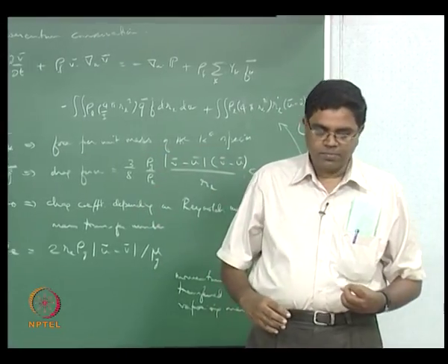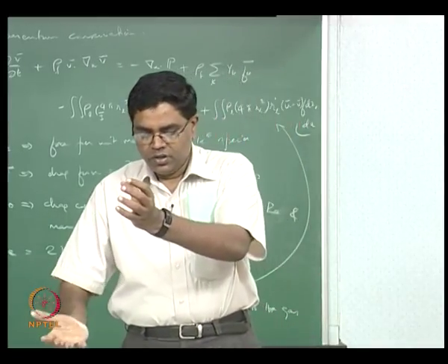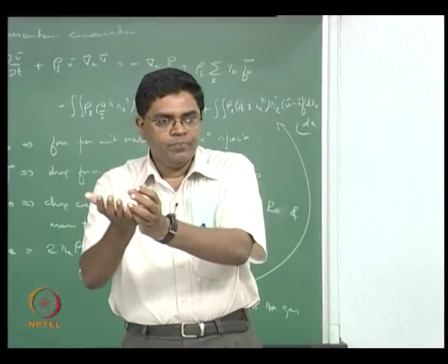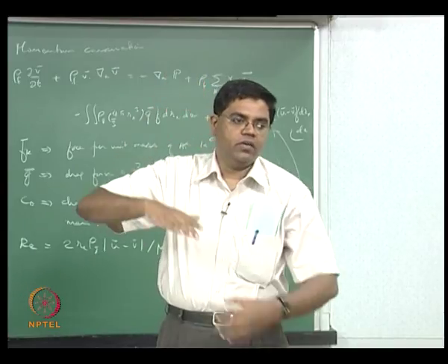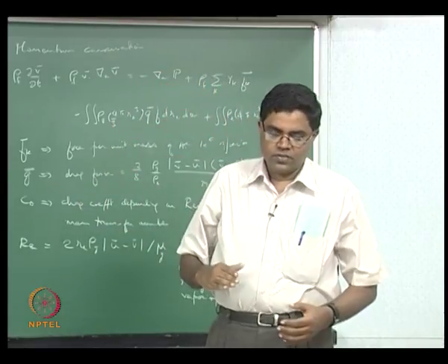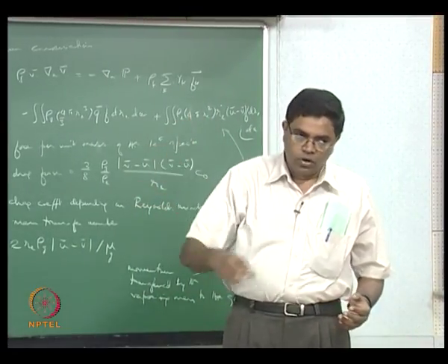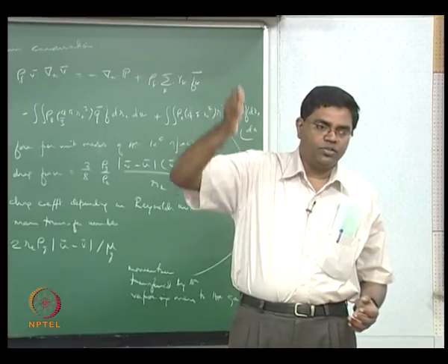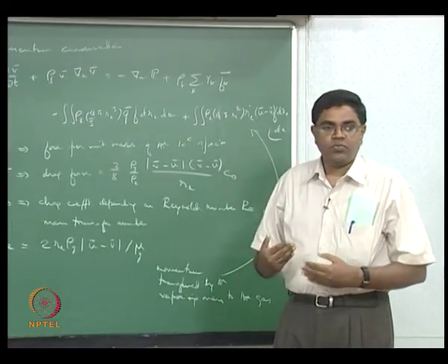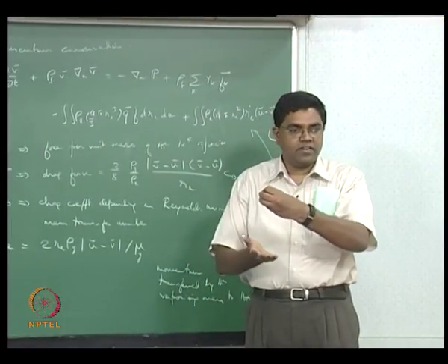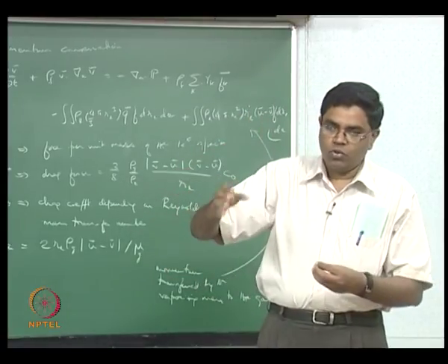So a simpler experiment for that would be, if you now have a droplet and then you have, let's say, a gas flow coming from the bottom, you now have a flame that is getting elongated along the flow direction, right? And you could still think about something like an envelope flame that is enveloping the droplet all around but getting elongated along the direction of the flow, right? But then as you now increase the relative velocity between the droplet and the gas, you get into a situation where you no longer have an envelope flame, you now have what's called a wake flame.